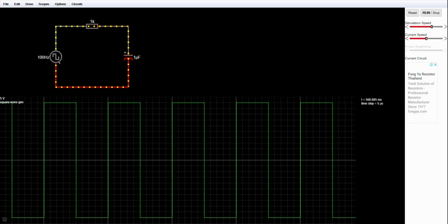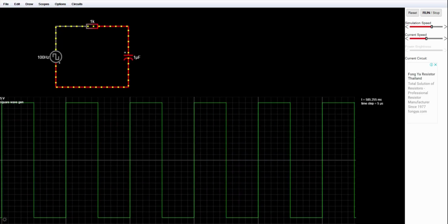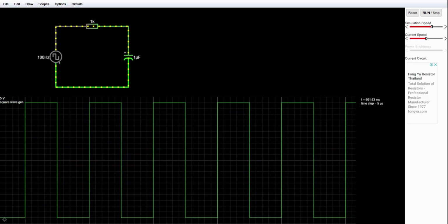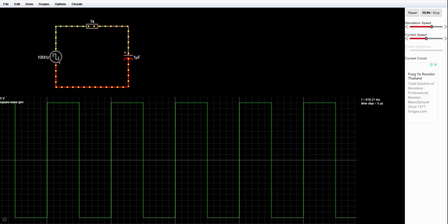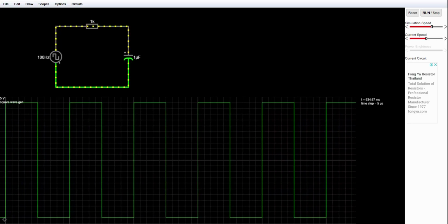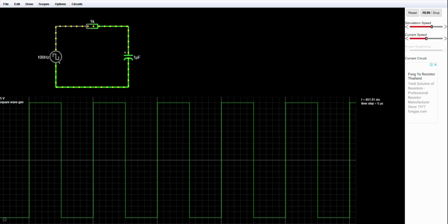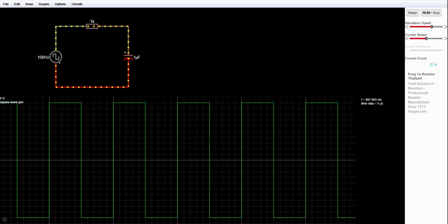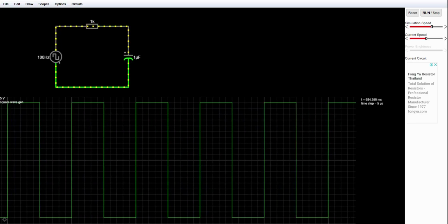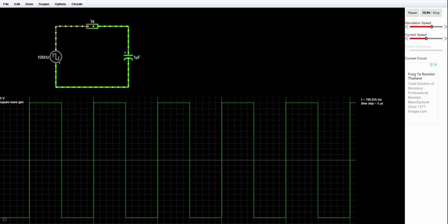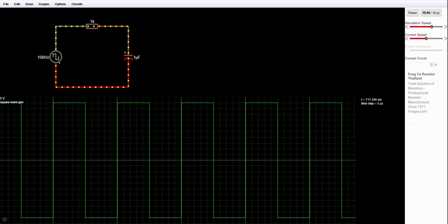It cannot show current waveforms by default. You've got to change certain things if you want to display a current signal there, but a DSO basically just measures voltage. So what we'll do in this experiment also is that we want to see only voltages. We don't want to see current right now, otherwise it will become a little confusing.